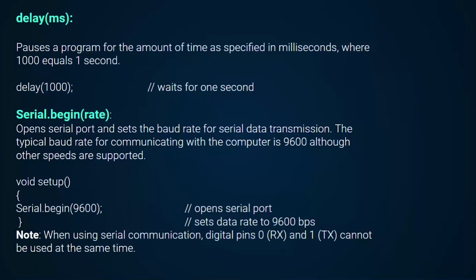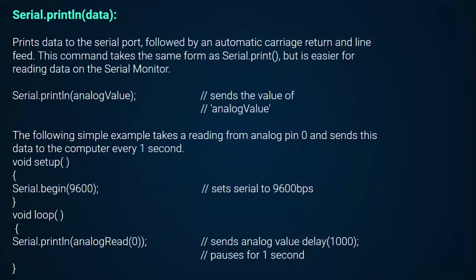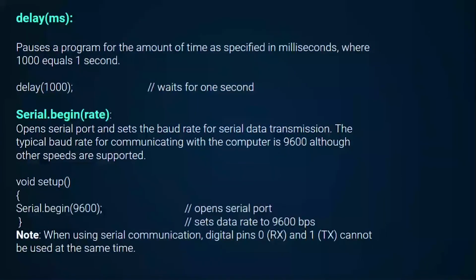When we say it will open the serial port, does it mean the user is going to input some values in the serial port so that it will be processing? It will begin the serial port, and whatever we have written in the program, it will execute, and you can see it in the serial board that we have talked about. It will start the transmission of data. We will receive data, we can write data, and whatever is going on, we can see it in the serial board. BPS stands for bits per second.